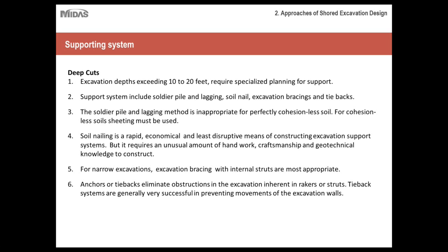So if you are dealing with open or closed excavation sites and you can do without struts, I would say it is better to go with tiebacks. And tieback systems are generally very successful in preventing the movement of the excavation walls.